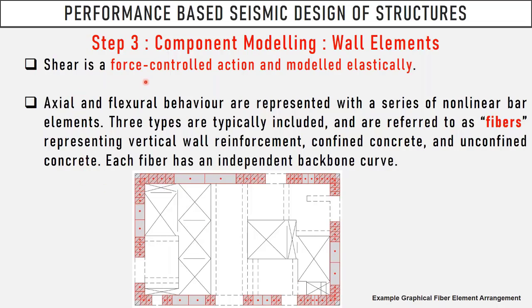As for shear, since shear has a brittle failure mode, it is modeled elastically. But in case of axial and flexural behavior, we use fibers, which have basically three components: you have the reinforcement, represented with red dots here. We have unconfined concrete, which is the panel of the walls, and you have confined concrete, which is the end zones of the walls.